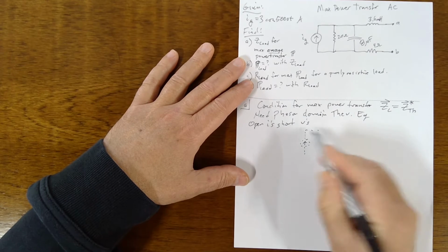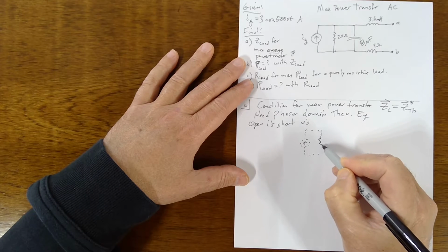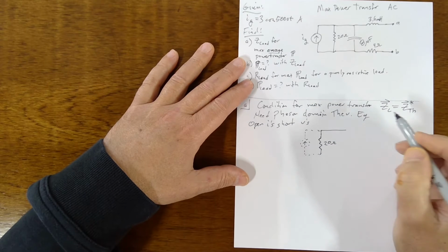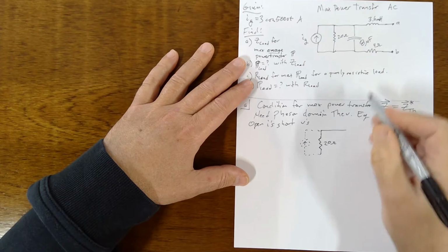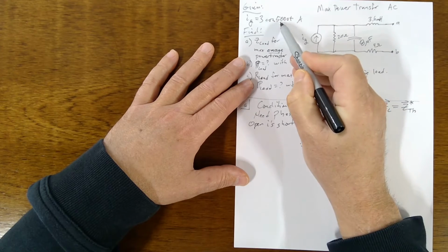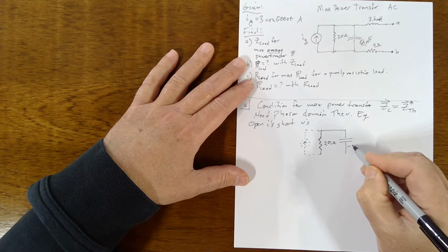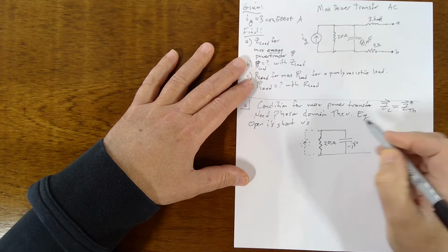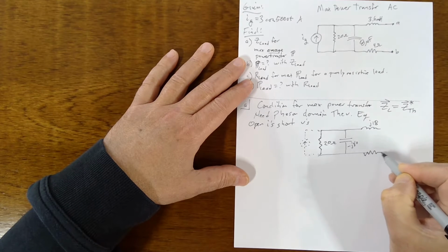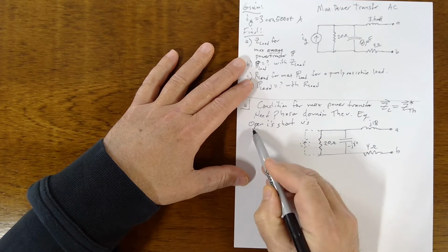All right, there's this I. We're just going to open it, or take it out of the circuit, make it like an open circuit. And at the same time, I'm going to put in the phasor domain equivalent for each element. The 20 ohm is just 20 ohm, but for the 8 microfarad cap, if you do the calculations at 5000t, which I'm going to skip, and calculate the impedance, which we've done before, it's not that hard, you end up with minus j40. Then this inductor likewise ends up being j18, and this resistor just comes straight across as 4 ohms. So we've got this situation just by opening the I's and shorting the V.